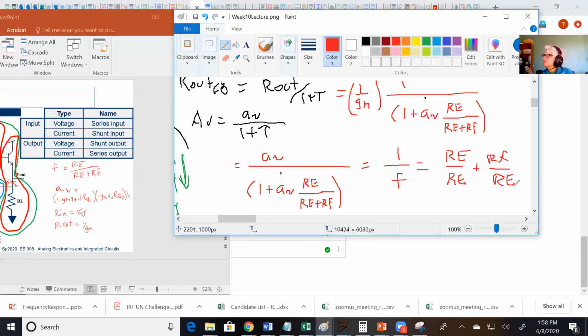So, are there any questions on what happened there? Just to clarify for F, it's just the external circuitry on the outside of the op amp. Yes. So if you circle all the vanilla amplifiers going from the input to the output, whatever's left is your feedback block. If you're designing your own circuit, then you know where the amplifier is already. But if somebody gave you something where you didn't know which part is the feed forward amplifier and which is the feedback amplifier, then you go through this process.